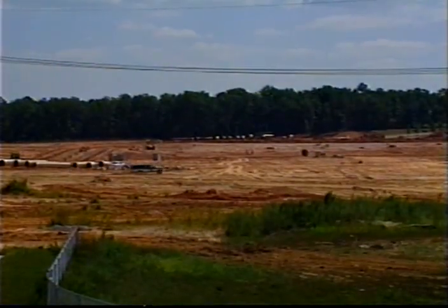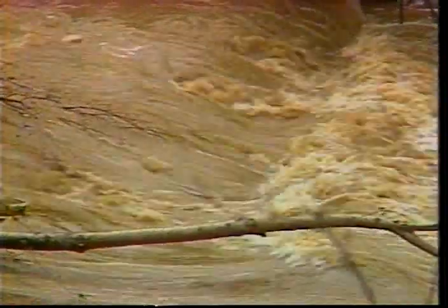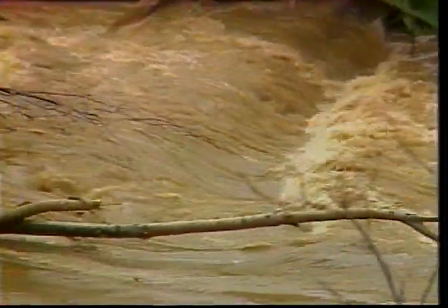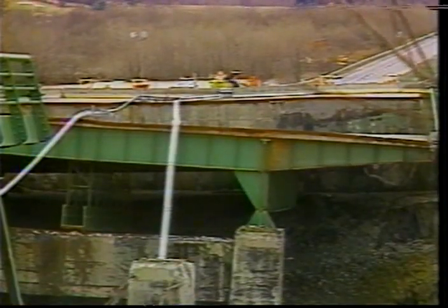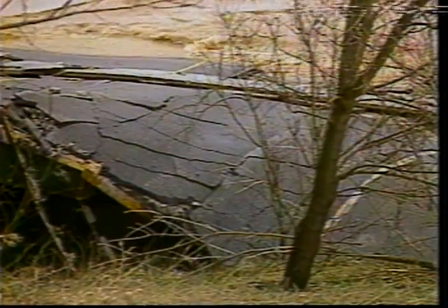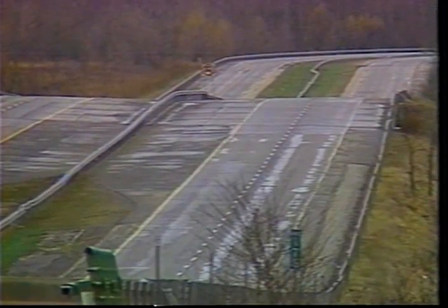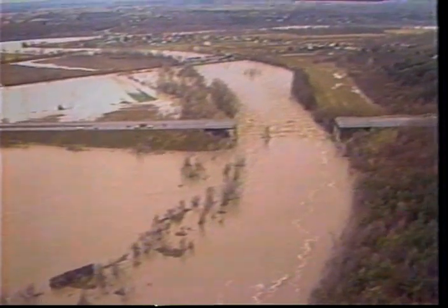Deforestation, land changes, and development can gradually change the nature of a watershed, which can cause normal rainfall to accumulate in waterways more rapidly, increasing volumes and velocities to new record flows. Situations which were adequate at the time of construction can change. The Schoharie Creek Bridge failure, which occurred in New York in 1987, was due to scour. The magnitude of this tragedy is a reminder of the necessity of periodic underwater inspection and careful evaluation of foundation conditions.